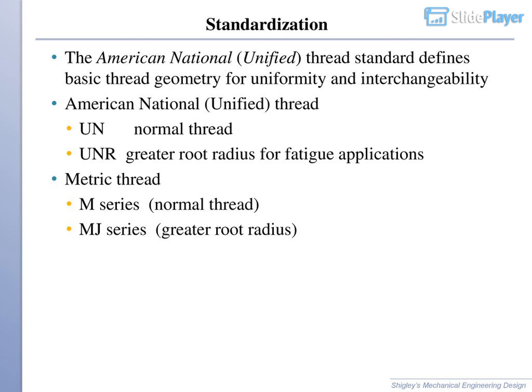American National Unified Thread, UN normal thread. Standardization: the American National Unified Thread Standard defines basic thread geometry for uniformity and interchangeability. UNR has a greater root radius for fatigue applications. Metric thread: M series, normal thread. MJ series, greater root radius.